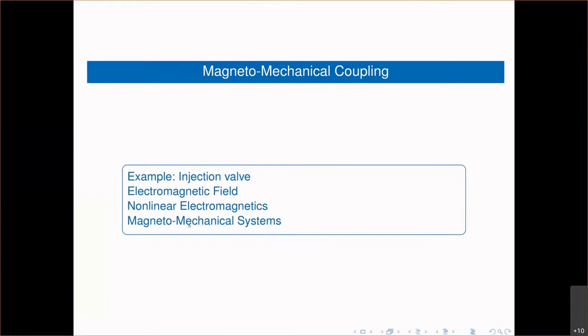And we have a second coupling, which is a very nasty thing, and that are the eddy currents being induced due to moving electric conductive bodies, and these bodies even get into contact. So what to do with the finite elements you have in the air gap before the air gap closes. We will have here some ideas or provide you some ideas how you can solve it.